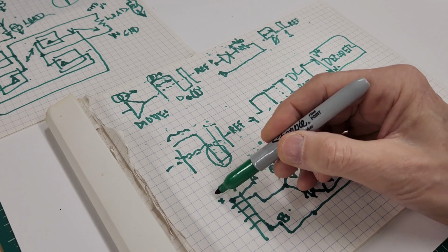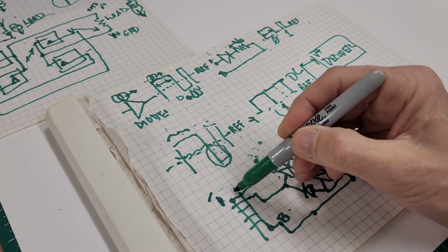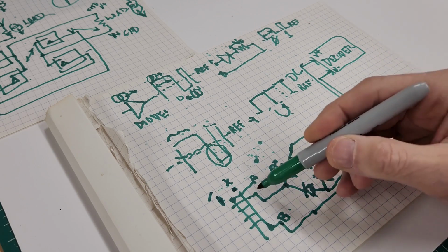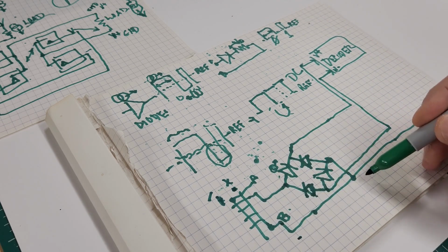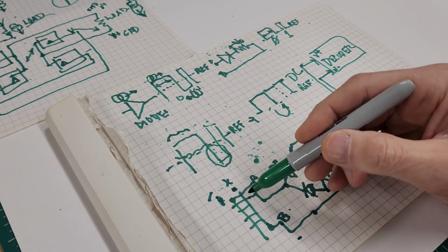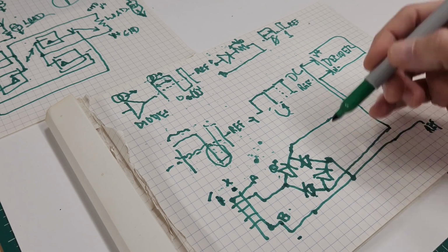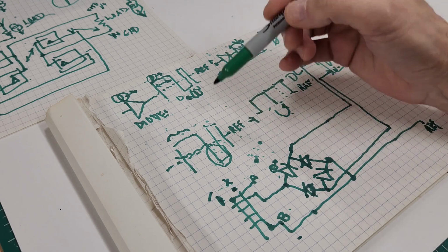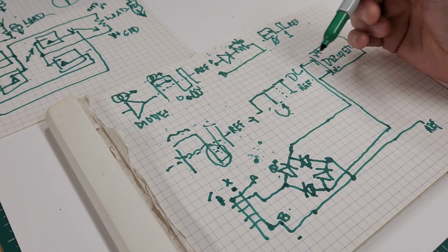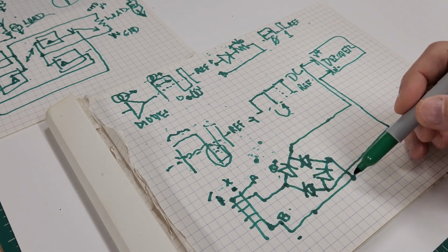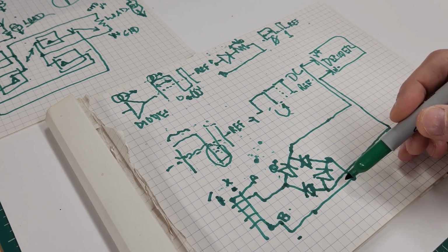So we have that same path working, even though I added two diodes. But now what happens when I put the negative here and I put the positive here? Now there's a positive down here, and current wants to flow this way. So now we're talking about this portion of the signal, where the currents are reversing on that AC.